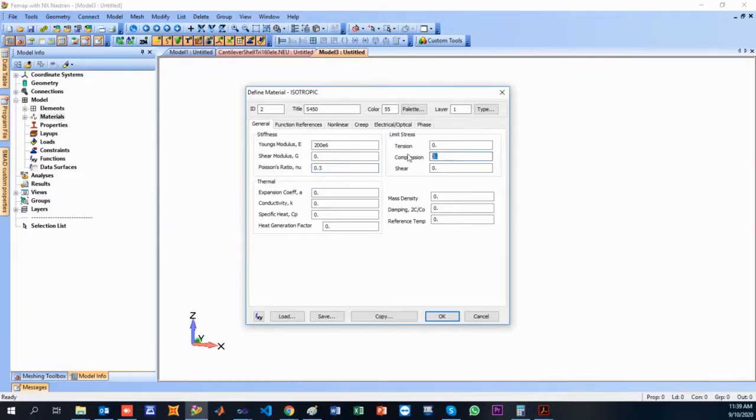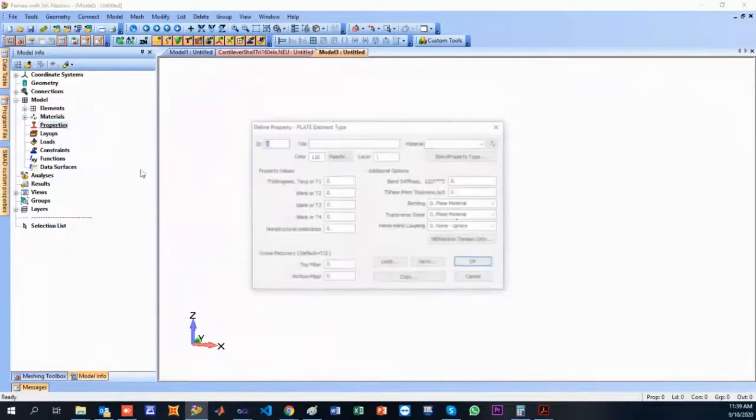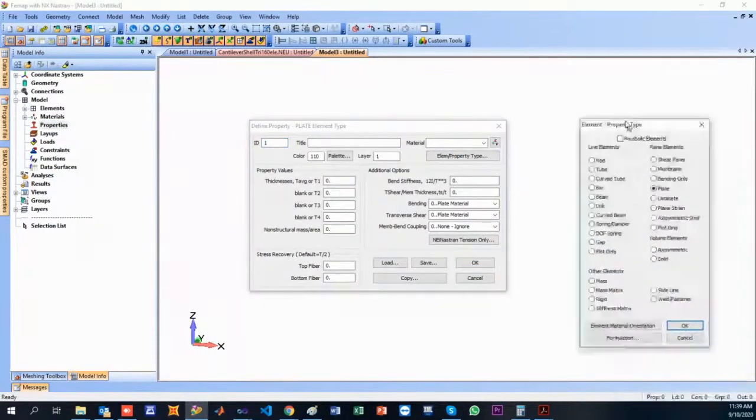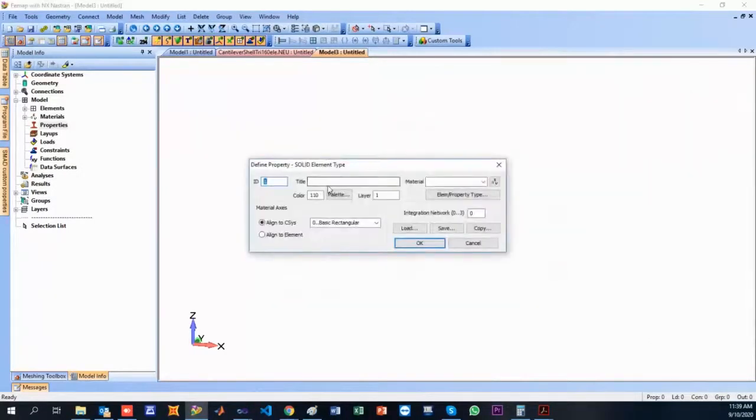which is 450 megapascal of yielding stress. Okay. And then I will have to develop, first of all, my solid concrete. So in this case, this will be hexa C45 for my concrete. I will need to develop also hexa S450. Why? I will also discretize the plates at the supports in order to avoid local failure.